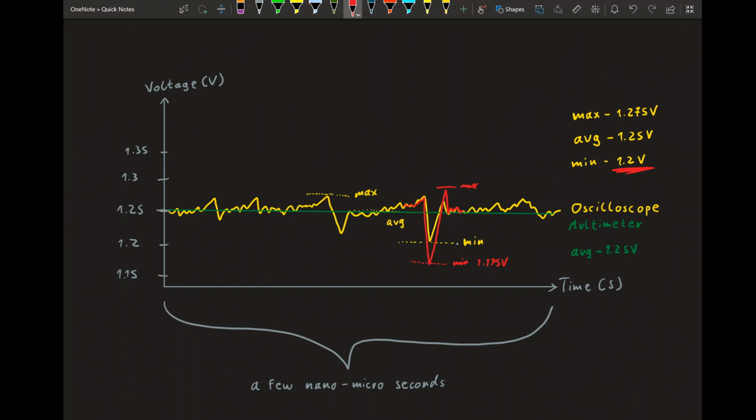And that's really what it's all about. That's what the oscilloscope can tell us. We can take two VRMs, put the same load, the same average voltage on them, and then observe what happens. And the VRM that will drop lower is the worst performing one, and it's going to need mods, or you're just going to need to run a higher average voltage to get the same overclocking capability out of it, because again,